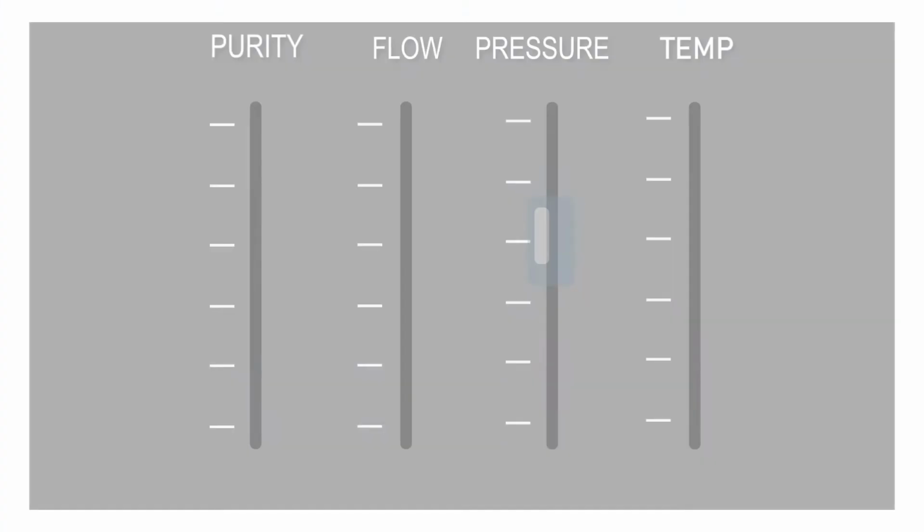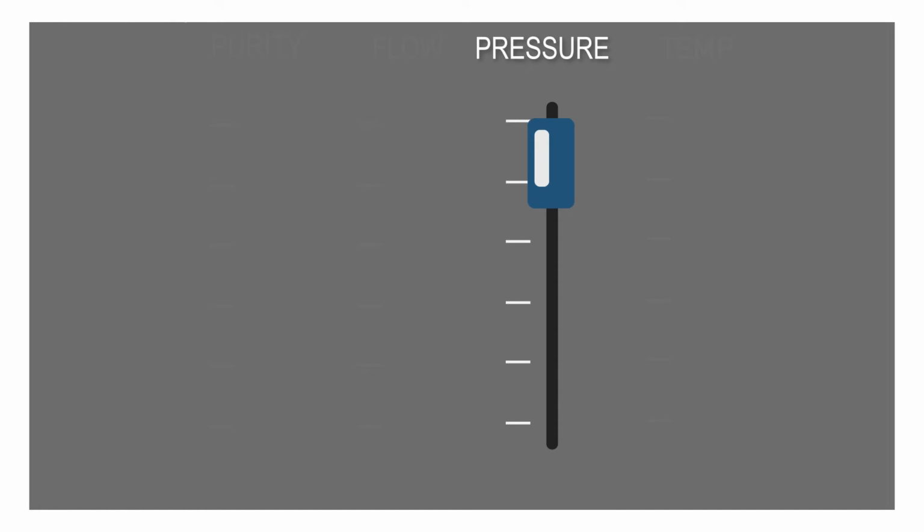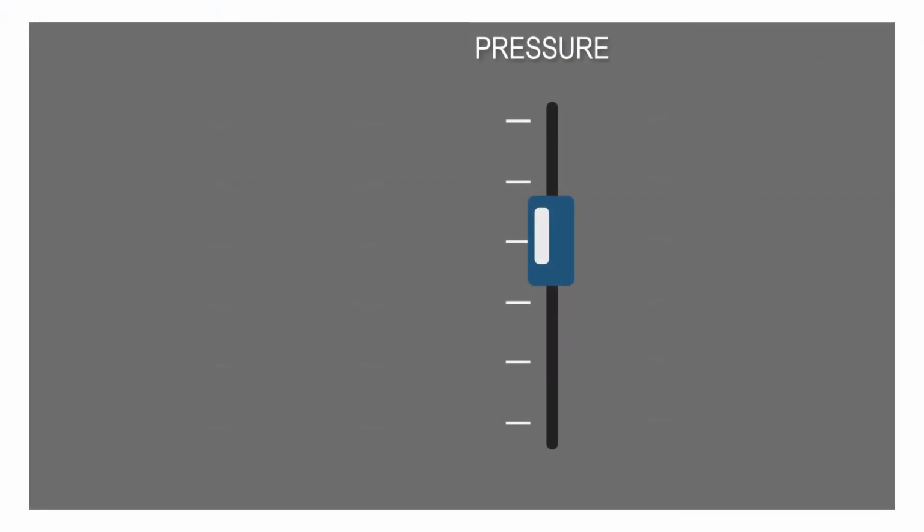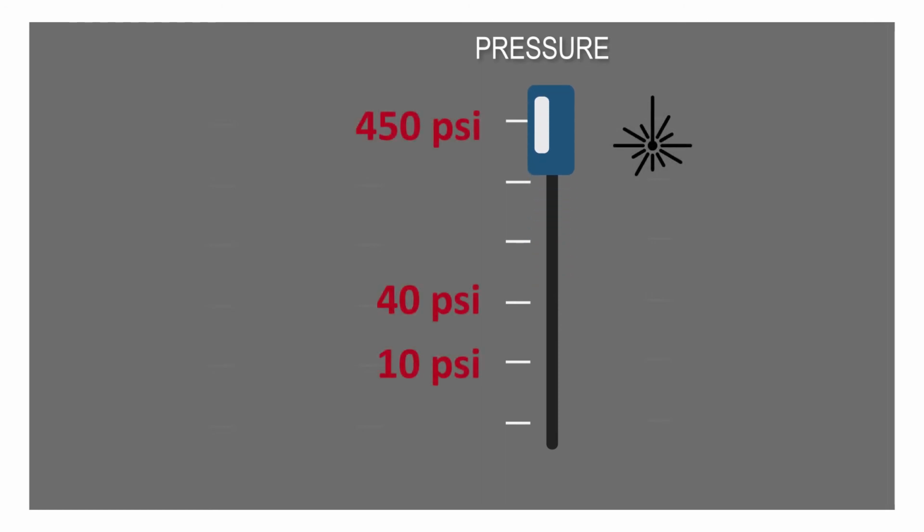Yes, we often come across the second and third patterns, but we're always happy to help to size the right system for you. Moving on to the issue of the required pressure. Clearly, the pressure needs to be high enough to meet the need. But the pressure at which the nitrogen is produced also impacts the capital cost and the operating cost of the generator. To give you some examples, for laser cutting, maybe around 450 pounds per square inch is required.